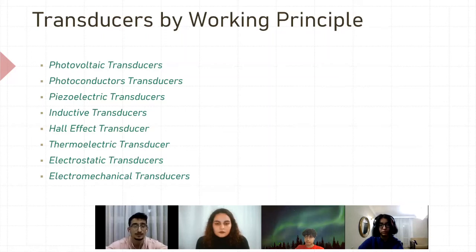of piezoelectric transducers. An inductive transducer working on the principle of electromagnetic induction measures the change in inductance between two coils. Physical quantities such as displacement, force, torque, acceleration can be measured by changing the inductance thanks to the moving core between the coils of the inductive transducer.